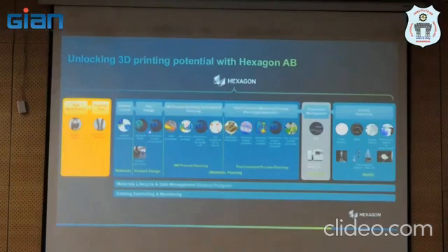As I said, we have to test with different loading conditions. Once I have this, then I go for data preparation and a feasibility study. Then we can also plan for post processing. After printing, does it require any coating? As you know, with some of the printing processes, we may not get the required surface finish. Then we have to go for machining, polishing and other things. So those things can be defined over here only. Then we manufacture and inspect.